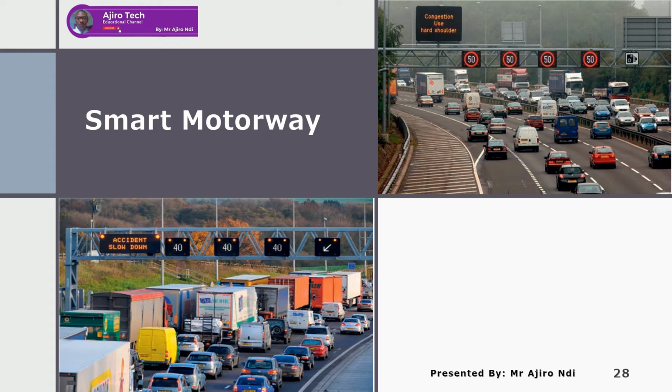It does this by detecting a change in frequency of the radar signals when it is reflected back off an oncoming vehicle. This has an advantage over the induction loop system because it is not susceptible, rather, to damage caused by potholes or erosion in the road.